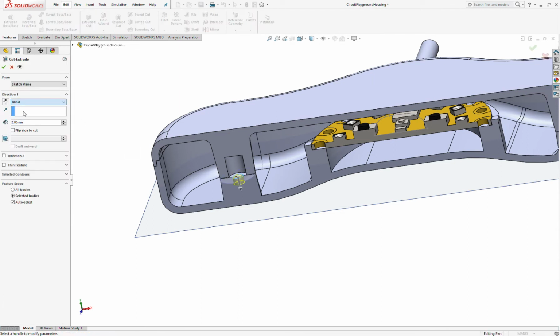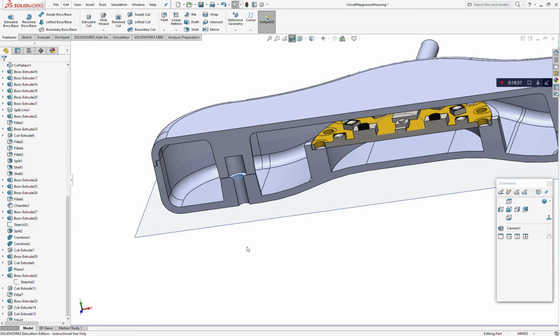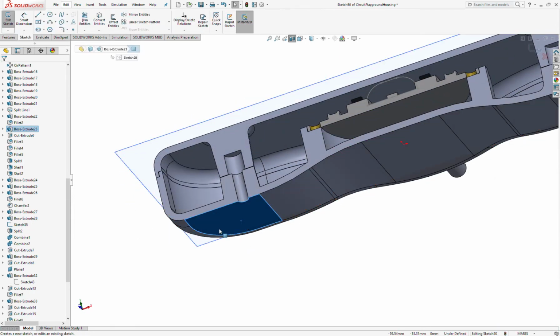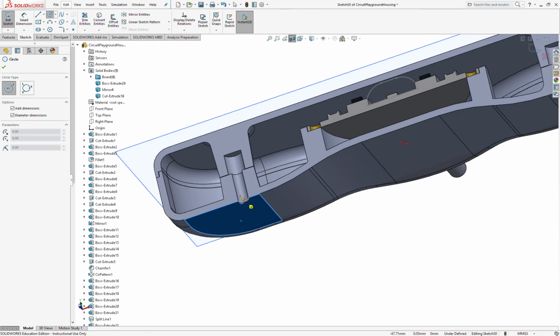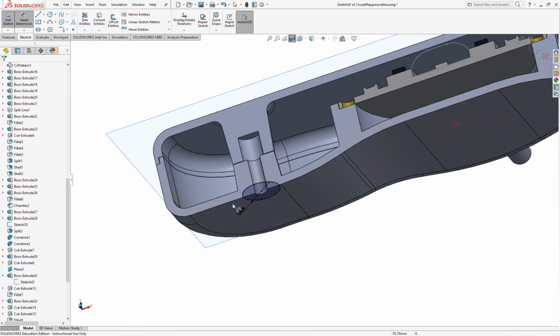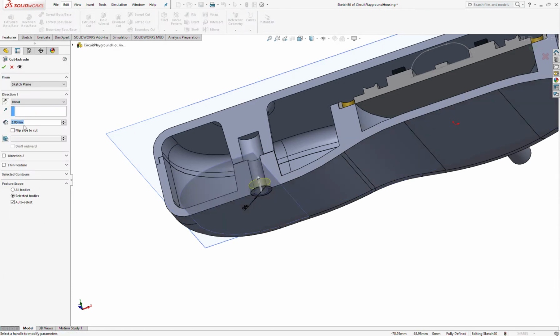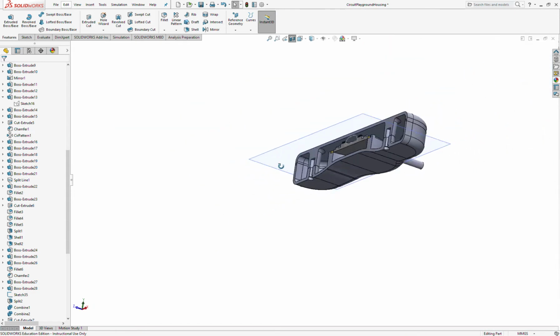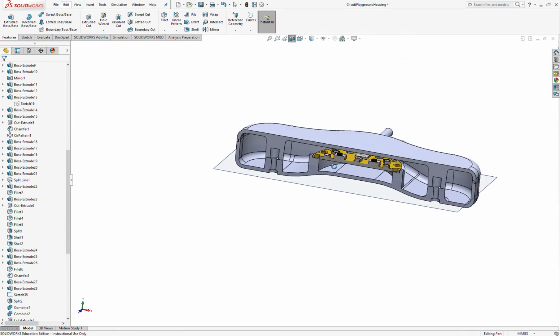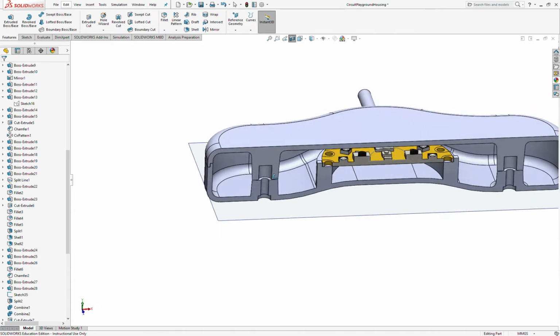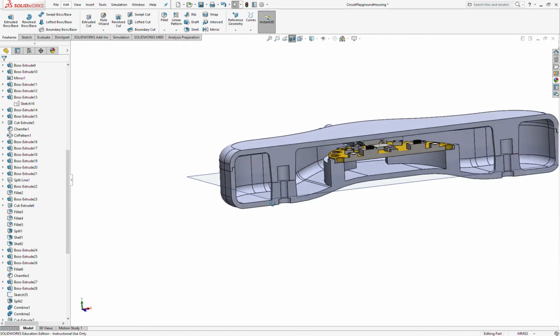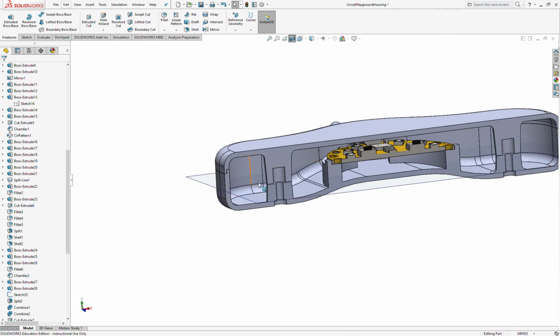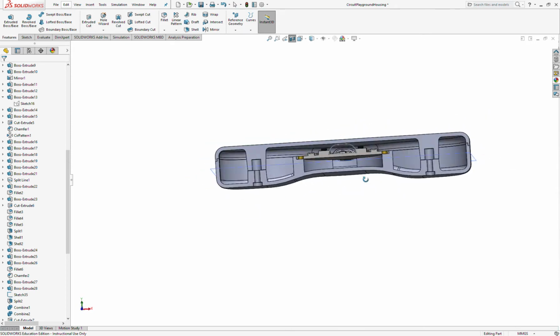Once again, I'm making these numbers up off the top of my head, so when you're actually using screws, you'd measure them, or you'd look at the dimension drawings. Usually, if you're getting them off McMaster, they're dimensioned already. Is that 5, right? There we go. So we've got our 2 screw holes, which are excellent. If we wanted to do a rib, we would just do sort of an extrusion along the inside. I think we're okay for now.